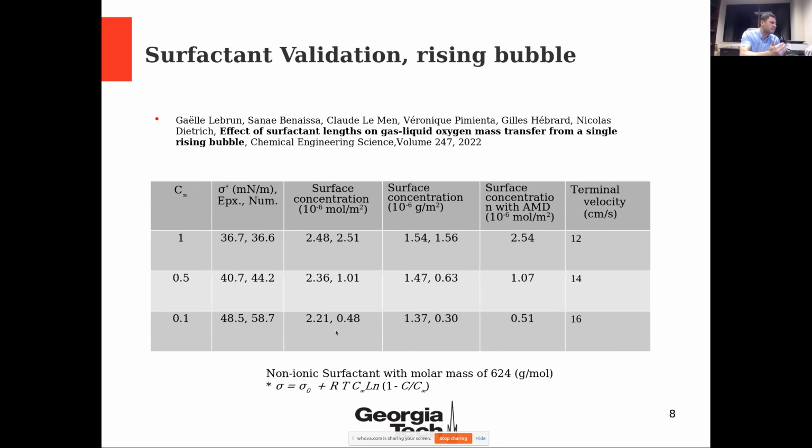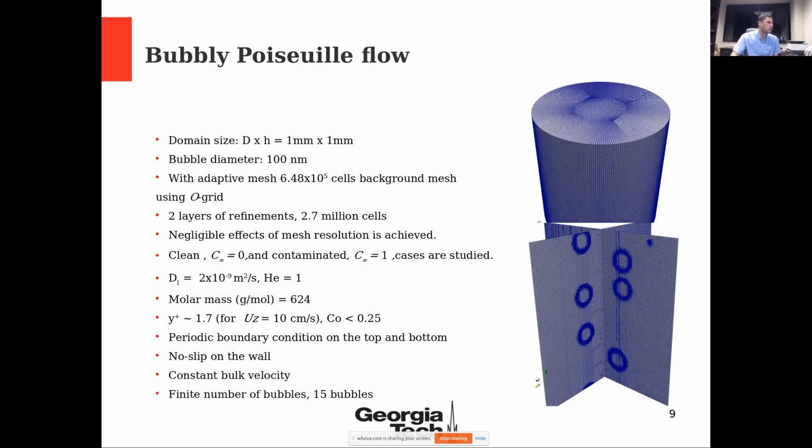So then we continued with maximum concentration, or C infinity, equal to 1 in a Poiseuille flow. Again, I don't want to go through all the numerical details. Imagine an infinite pipe where we added the source term in the FV option from the OpenFOAM perspective. As long as we are interested only in interfacial mass transfer, not the wake of the fluid, I kept the adaptive mesh refining only the interface, not the wake, to resolve the interfacial mass transfer as much as possible.